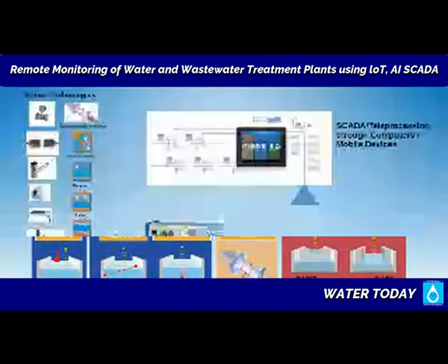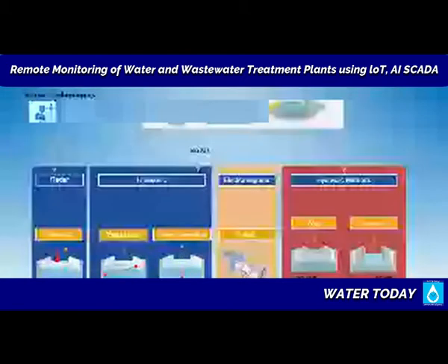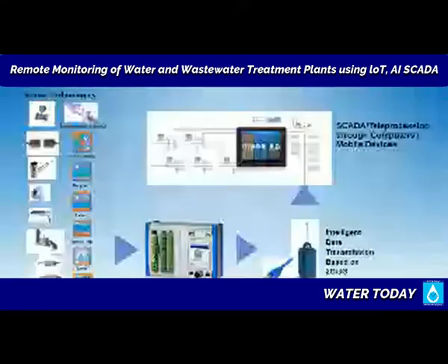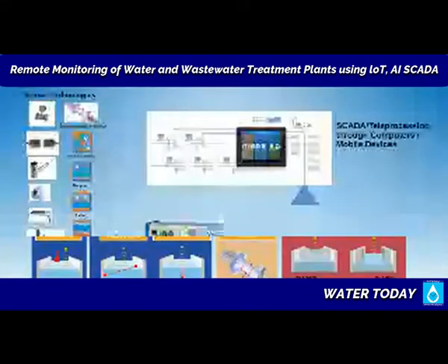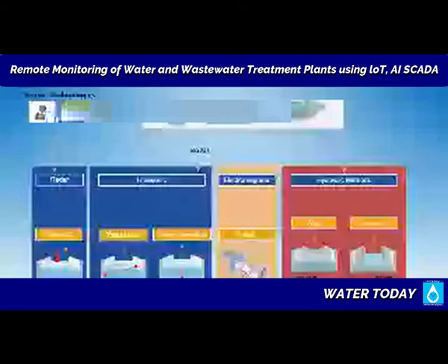The sensor can be fitted on top of the pipe outside, externally, and from there the ultrasound signal can go and measure the velocity in the pipe. Now, there is the Doppler cross correlation measurement system, which we discussed earlier, which is about looking at particles entering the medium, in water, and seeing how they travel and what distance they travel so that you can use that velocity measurement into volume flow calculation. That's the cross correlation technology.